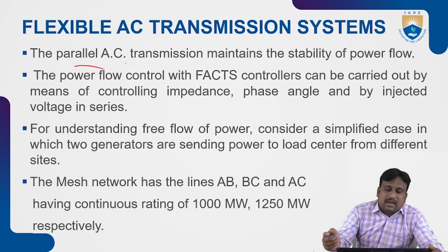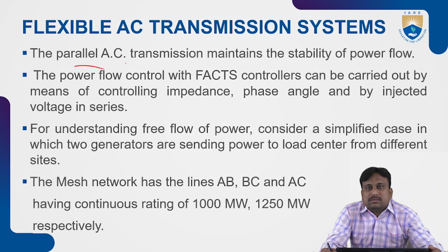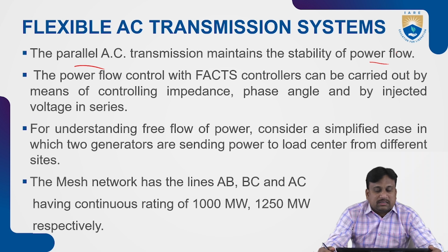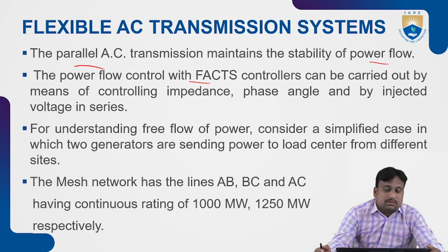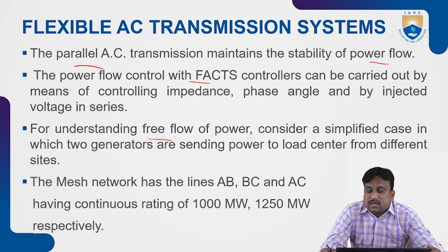So here the parallel path of the AC transmission is ready to maintain the stability of the power flow condition. Power flow control with the FACTS controllers can be carried out by means of controlling impedance, phase angle, and injected voltage in series. For better understanding of the flow of power, it should be considered with a simplified case in which simple